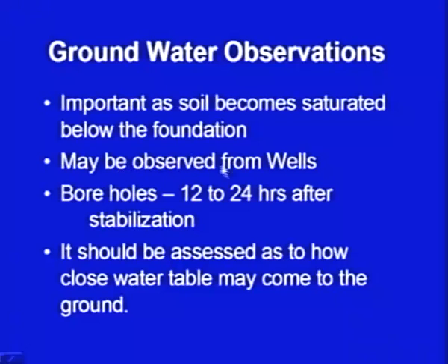You can get it from the wells or from the boreholes which are advanced during the exploration program, and for that at least 12 to 24 hours should be given for the water table to stabilize. After the water table stabilizes, the water table depth should be measured and assessed as to how close it may come to the ground or to the foundation. That is what we should assess from the field exploration program.